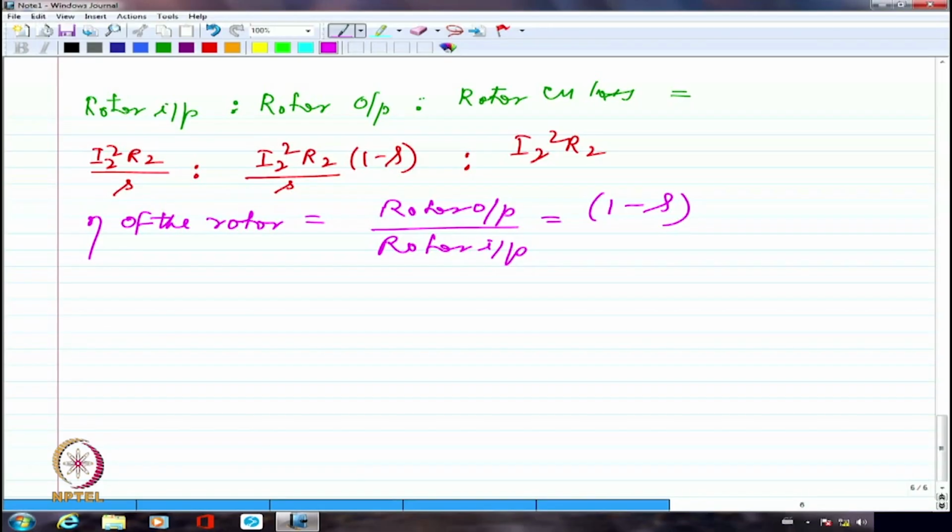So lower the speed of the induction motor, more is going to be the losses or less is going to be the efficiency, right? So if I have a larger rotor resistance for a given current, I will have larger rotor copper losses. For a given chunk of total rotor input power, I will have larger chunk of rotor copper losses, which means I'm going to have less and less mechanical power. If I have less mechanical power, in all probability, it will be able to rotate only at a lower speed. So the slip is going to be larger.